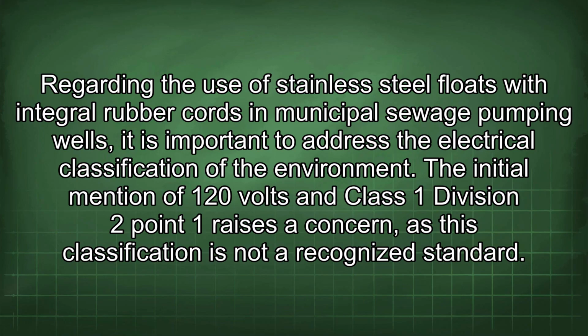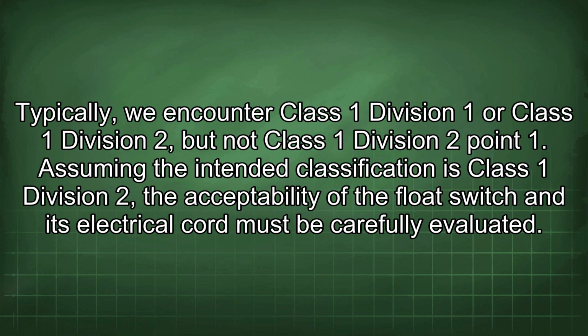Regarding the use of stainless steel floats with integral rubber cords in municipal sewage pumping wells, it is important to address the electrical classification of the environment. The initial mention of 120 volts and Class 1 Division 2.1 raises a concern, as this classification is not a recognized standard. Typically, we encounter Class 1 Division 1 or Class 1 Division 2, but not Class 1 Division 2.1.